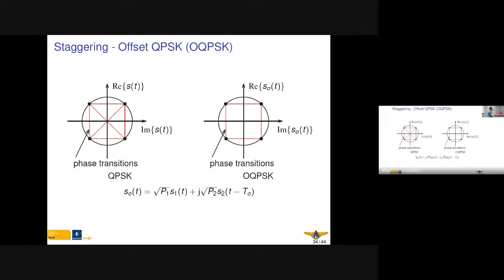And this happens when the signals before the amplifier are not absolutely binary. When we generate the signal on board the satellite or at any transmitter, this is always the case. We generate a signal that is not absolutely binary, because we do that in a digital domain. So the signals usually have a certain bandwidth also before the amplifier, and that's why we have these transitions.